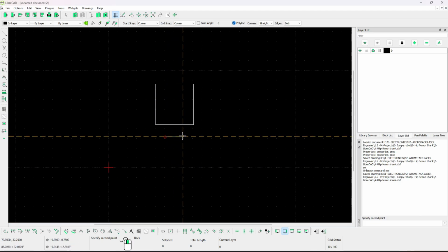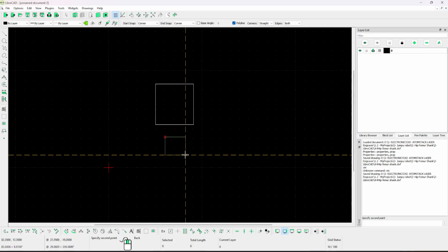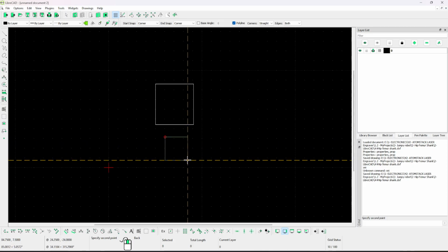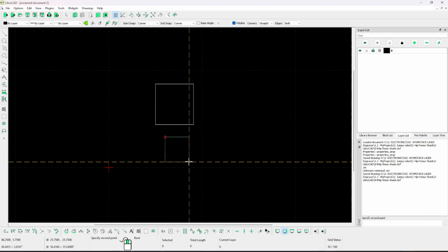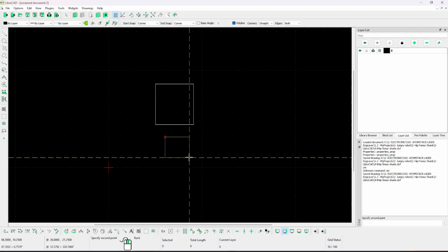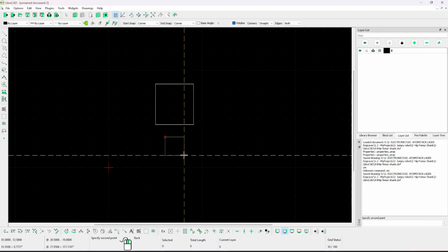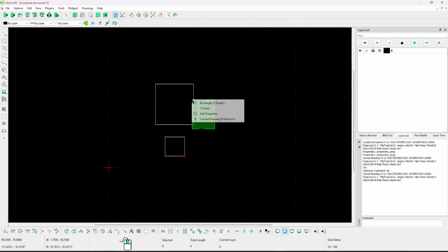Maybe I say 20 millimeters. I've set my units to millimeters, and if I go below to the negative side, negative x axis, I can do 20 again. So make sure it's 20 20. Okay, so this is 20 20.